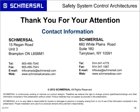If the question is a momentary push button, there are no momentary push buttons allowed as an emergency stop device. An emergency stop has to be maintained. It has to be a positive self-latching. So you hit it, it latches itself in, and it's either a push-pull reset or a twist-release type of reset. And the reason is the reaction of an e-stop.